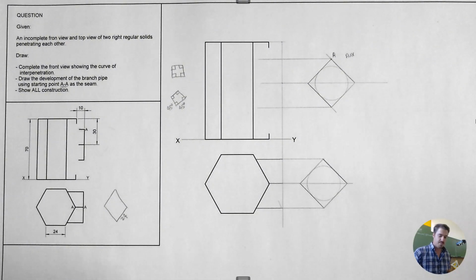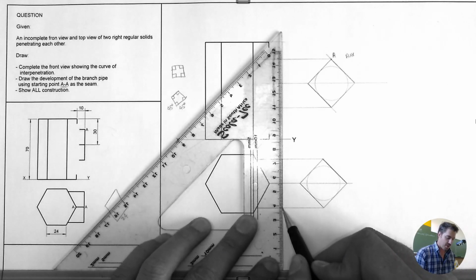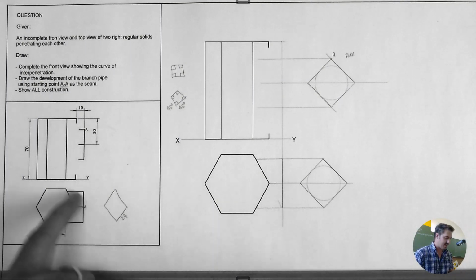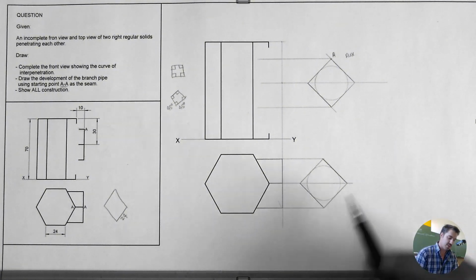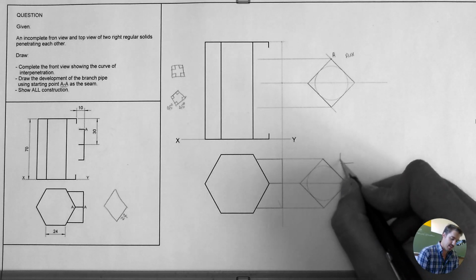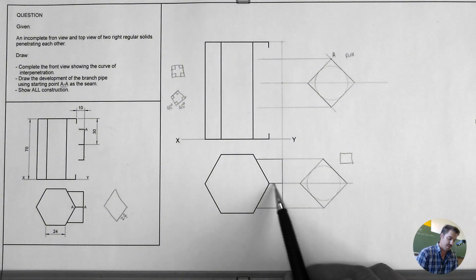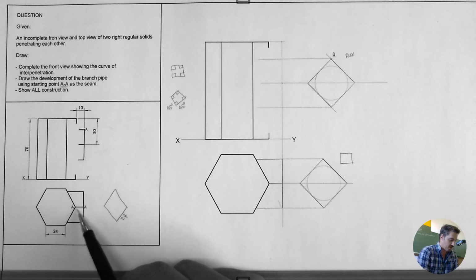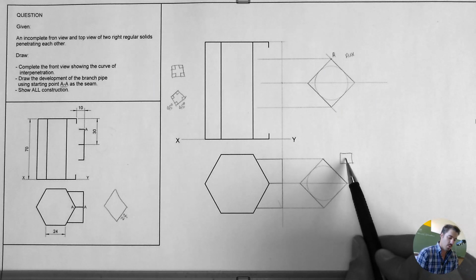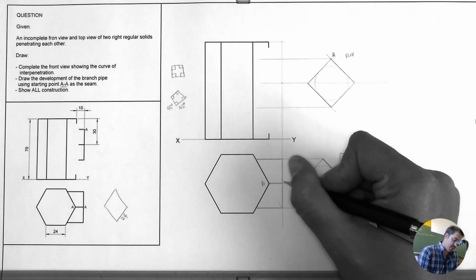Alright, now it should make a bit more sense when I told you that the way the branch pipe is looking, the way you can see it here, means it's the way it's supposed to be turned. If it was turned so it looked like this, then your auxiliary view, you see there's a midpoint here where one of the corners are. So if this midpoint was not there, you could have assumed they wanted you to draw the auxiliary view like this. But alas, that's what we have. So this is going to be the AA point.